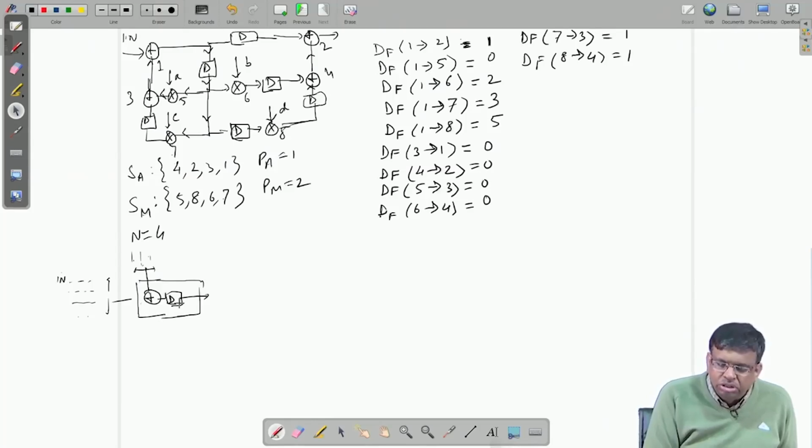So, at schedule 4, that is clock 4, the adder output is coming in the system. That means adder 1 output is born in not cycle 3, but cycle 4 because of one more delay inside. So, N1, I call it N1 for node, there is a node output 1, it is born in cycle 4,